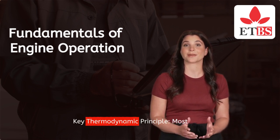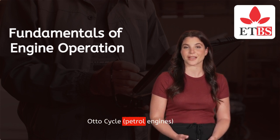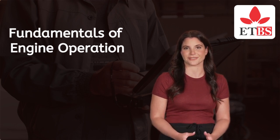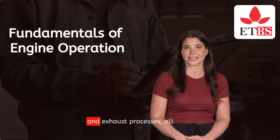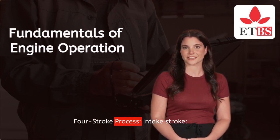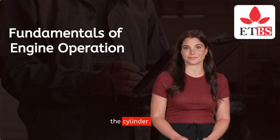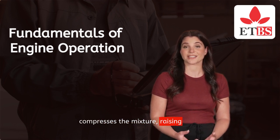Key thermodynamic principle. Most engines operate on the Otto cycle, petrol engines, or diesel cycle, diesel engines. These cycles involve the intake, compression, combustion power, and exhaust processes, all governed by the laws of thermodynamics. Four-stroke process. Intake stroke. Air-fuel mixture, or air in diesel engines, enters the cylinder. Compression stroke. The piston compresses the mixture, raising temperature and pressure.